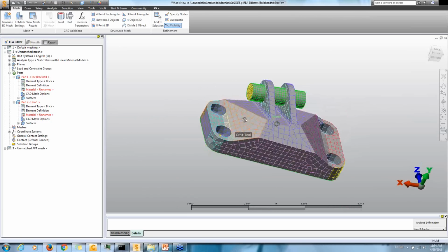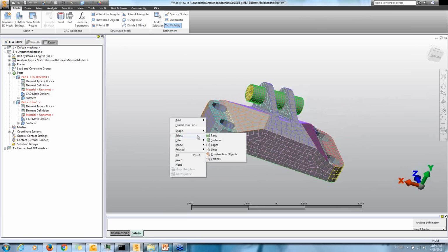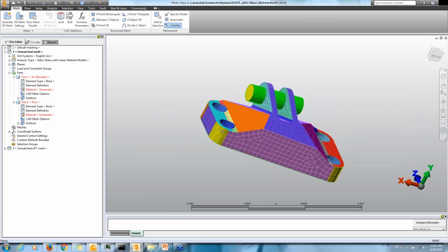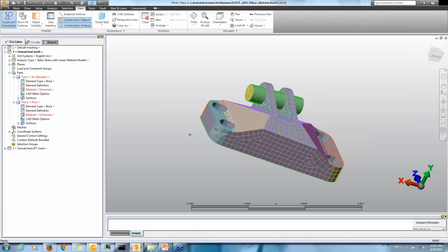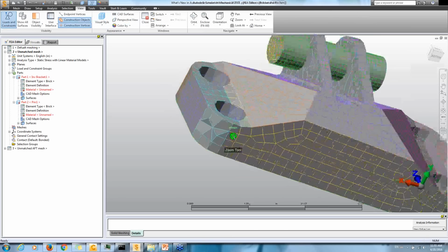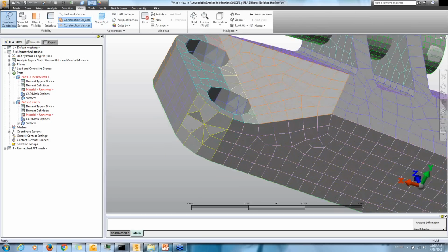And what we're trying to show here is what happens to our meshes when we use our default mesh style. Our default mesh style for the past 10, 20 years for surface meshing has been using a technique called advancing front, which means our surface mesher starts meshing a given surface from the edges of that surface and starts going into the center of that surface. And whenever we have that type of a technique, sometimes we represent a fillet like this using multiple triangles, which doesn't really capture that curvature properly.